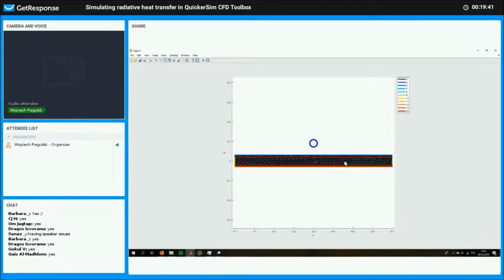The viscosity of water, between the range of 0 Celsius and 100 Celsius, so between the freezing point and the boiling point, changes significantly. I think it's like threefold basically. So it is a non-negligible effect in real life. Because the viscosity is not constant, it is defined by the temperature, we're going to need to iterate a few times between the heat transfer and the fluid flow.